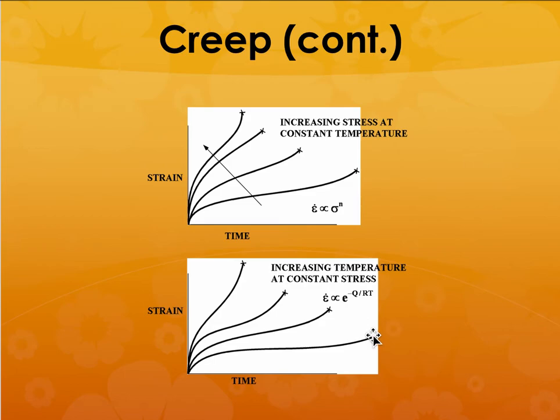You get more time before it will rupture. But as you increase the stress at the same temperature, the creep curve will shift to the left, and beyond a certain stress level, you are treading on dangerous waters. That component will fail almost instantaneously as soon as you go beyond a certain stress level.